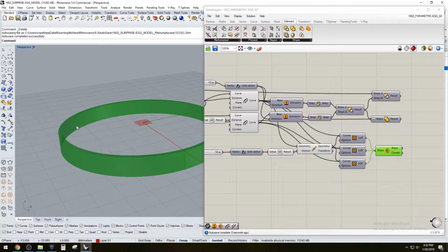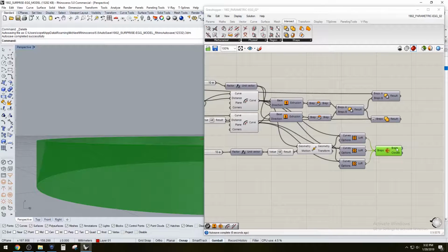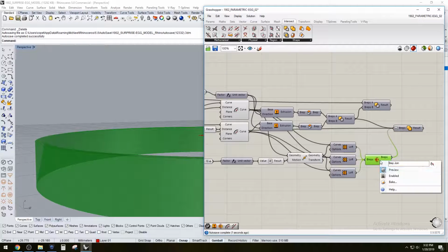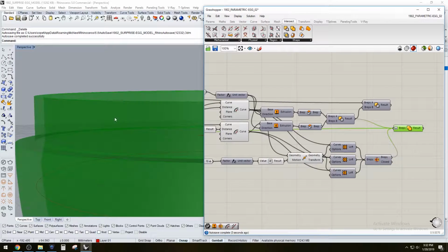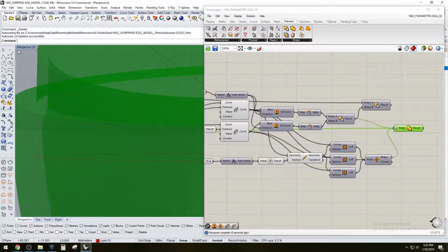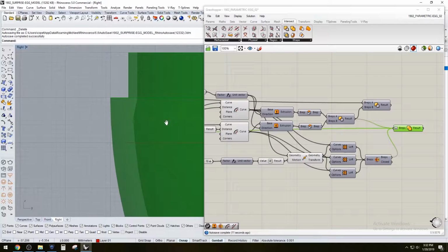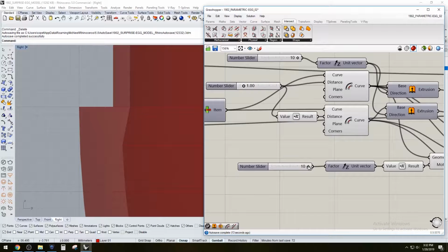we'll see that we have basically a solid B-rep, one closed B-rep, and that will be what we want to union also with this, and that way we have created that slope that we were looking for, so we can 3D print and also make it more sturdy. So you'll see here we can decrease it or we could increase it. We'll keep it at 5.